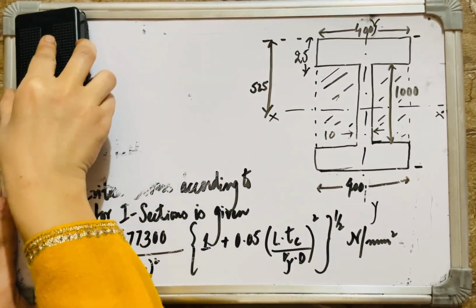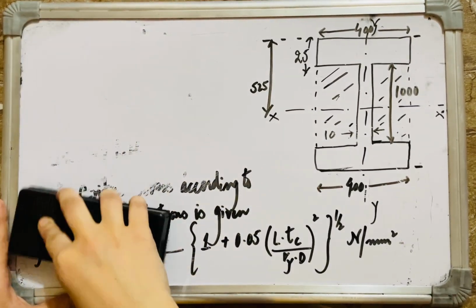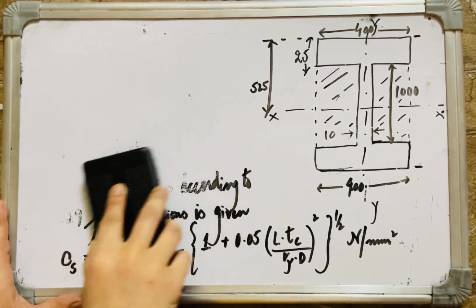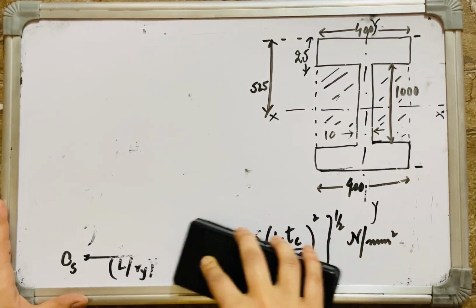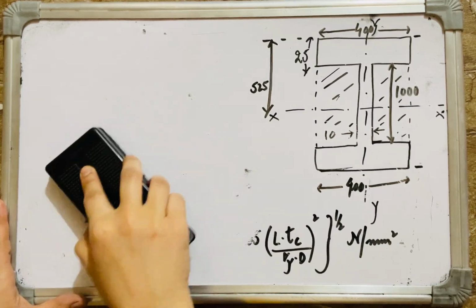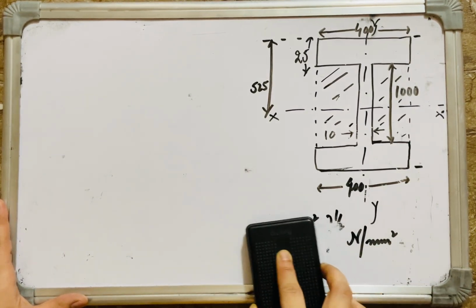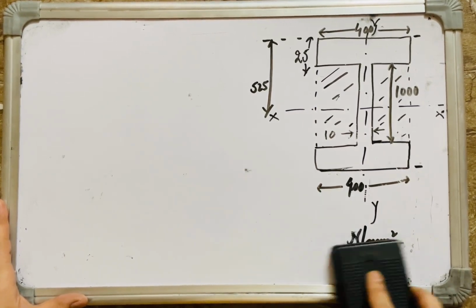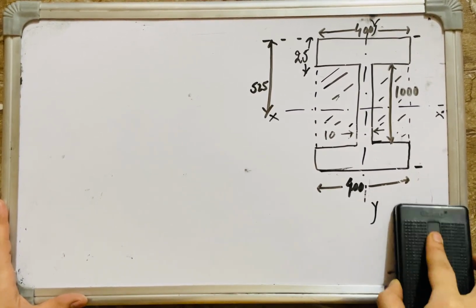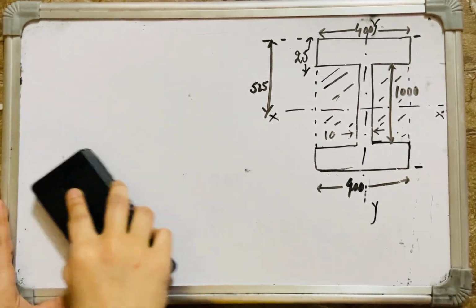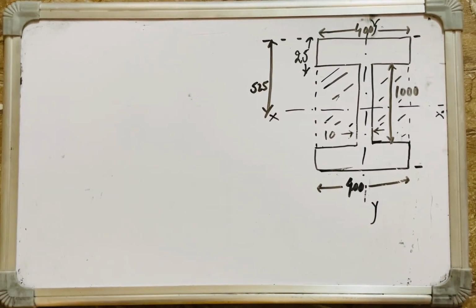Step by step, we are learning the process of designing the steel trussed bridge, and simultaneously we are also learning the steps of designing the plate girder bridges, because plate girder is the same thing. Cross girders in case of steel truss bridges are designed as plate girders.